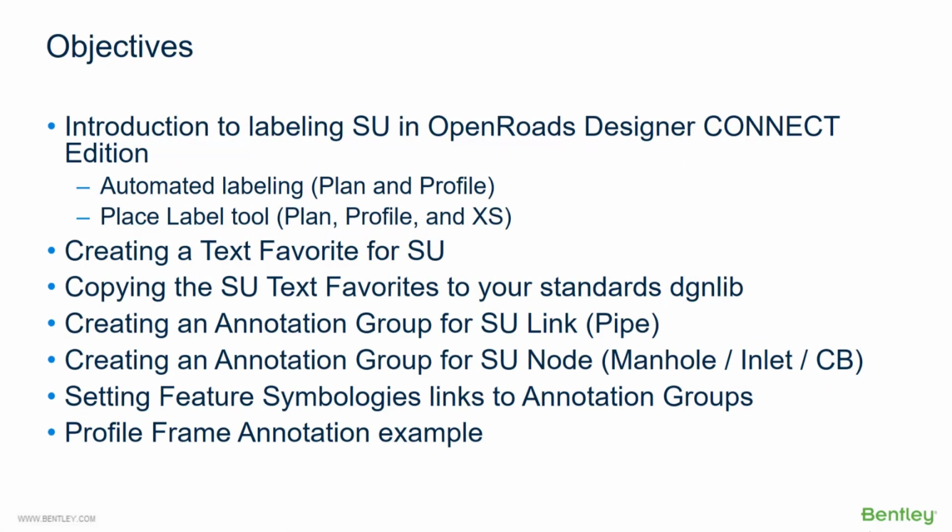The objectives of this training is to introduce labeling for subsurface utilities in OpenRoads Designer Connect Edition, and that includes automated labeling for plan and profile, and also using the Place Label tool for plan, profile, or cross-section. We're going to teach you how to create a text favorite for subsurface utilities, copying the SU text favorites to your standards DGN lib, creating an annotation group for a SU link or a pipe, creating an annotation group for a SU node, for example a manhole or an inlet or a catch basin, setting feature symbology links to the annotation groups, and also taking a look at profile frame annotation.